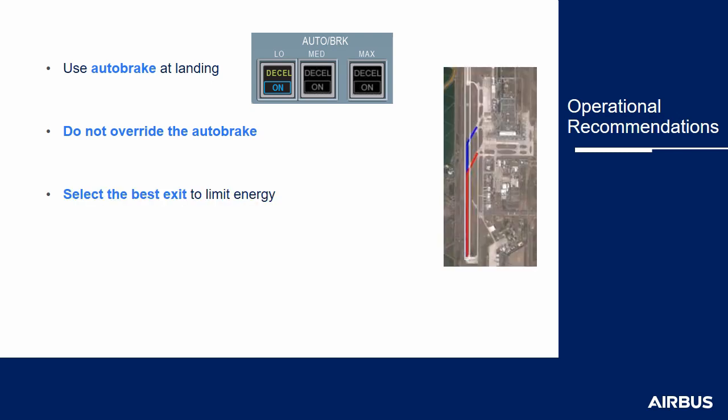When possible, select the best exit on the runway before landing and find a good compromise to limit energy in the brakes. However, we know that sometimes the flight crew may have a limited choice because of company policy or traffic control order.